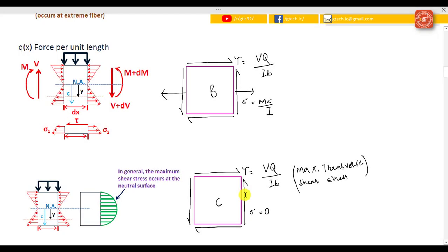At point B, when we put a small differential slice of our beam, we saw that we got both flexure stresses and shear stresses, and so we will look at that point as being an area where we have a combination of stresses that may be critical. One point that I want to make is that I'm looking at the cut below the neutral axis. Down here or above the neutral axis, the shear stress direction changes.